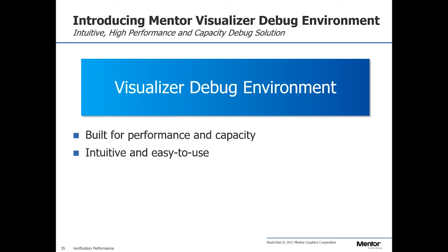I have to say I like the traditional Tcl debugger that comes with Questa, but I actually have started to use Visualizer, and I find things that take me 7 or 8 mouse clicks in the traditional debugger take me 1 or 2 mouse clicks, and everything is much more automated and synchronized.